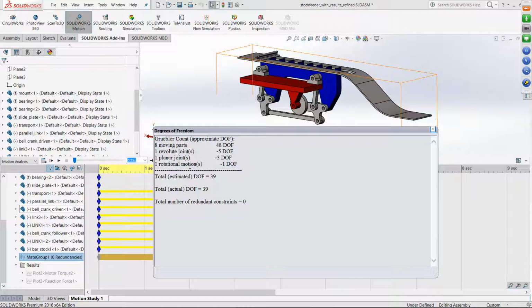Thereon we create joints which are going to restrict or constrain or guide how these degrees of freedom are going to move. So using that, you can see it will remove certain degrees of freedom. And finally we need to ensure, as I mentioned when doing it in the assembly, when we create the mates, that all these different joints or mates are created appropriately, such that the final balance is almost zero, or there are no redundant constraints in the setup.